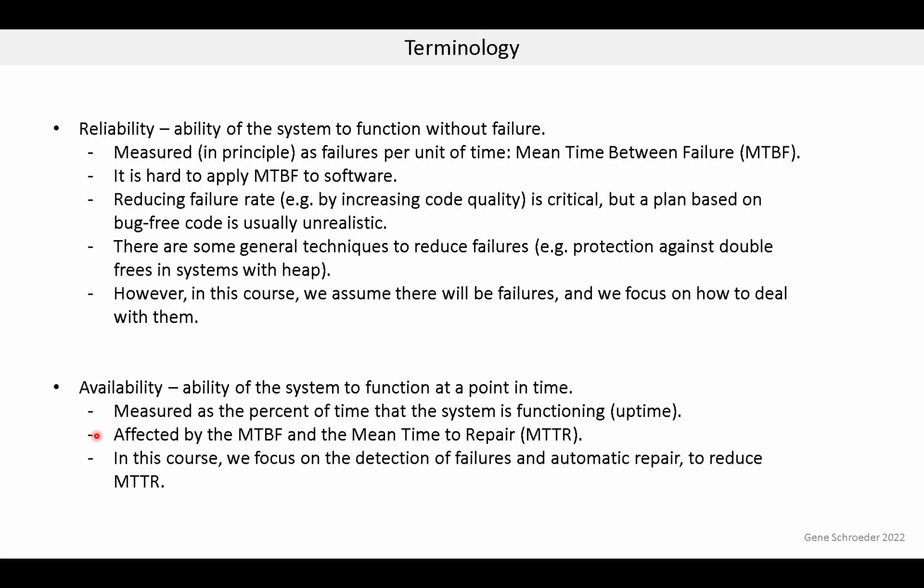Now, this is affected by MTBF. If you don't have any failures, you're 100% available. And it's also affected by the mean time to repair. In other words, once there is a failure, how long does it take until the system starts running again? And of course, that can depend on many, many things depending on the technology. In this course, we focus on the detection of failures and automatic repair to reduce mean time to repair. And this is things like an automatic system reset.